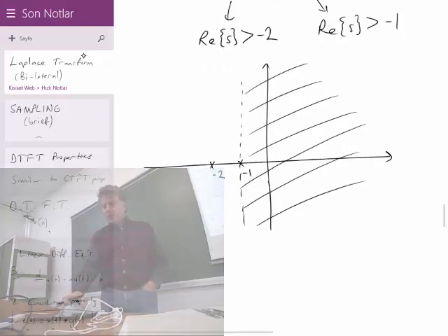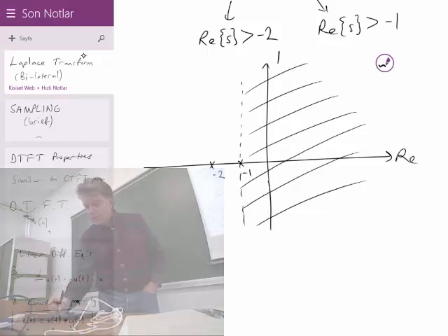And as you see, this region of convergence, where horizontal is real, vertical is the imaginary axis, this is the s-plane, indicates the region of convergence. And this region of convergence does not include a pole. And that is a rule. If somehow you encounter a pole inside your region of convergence, that means you're doing something wrong. A region of convergence never includes a pole.